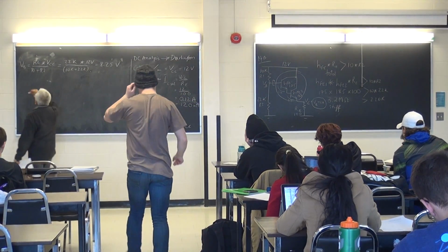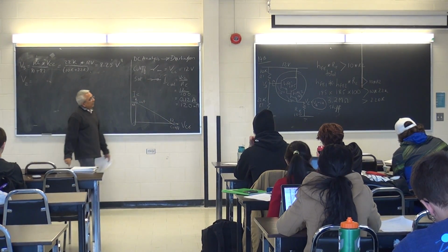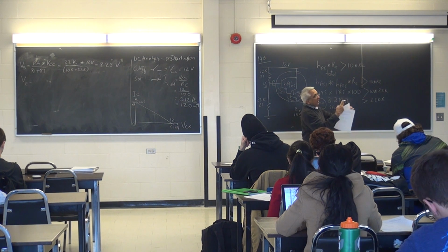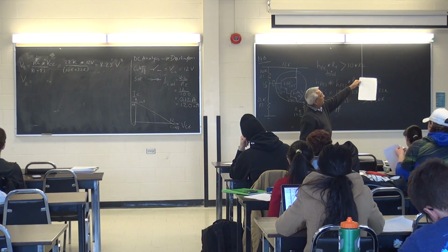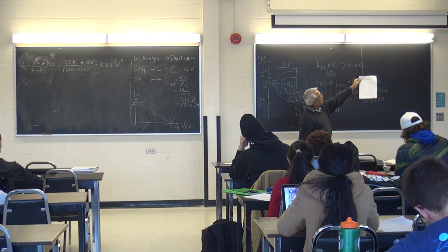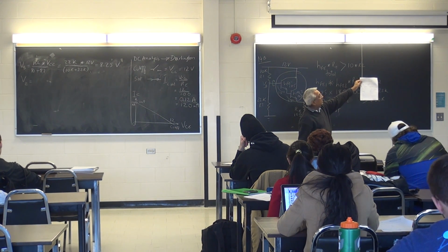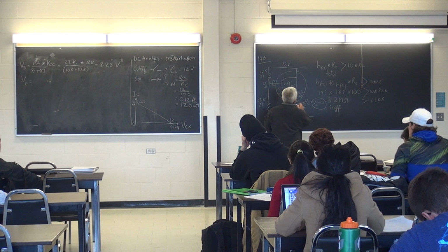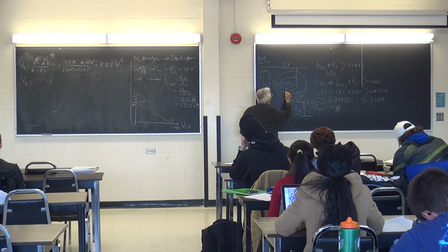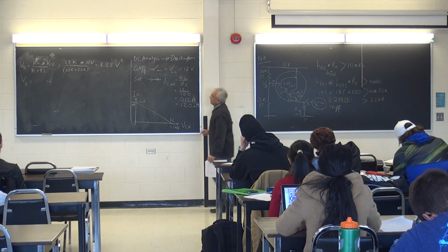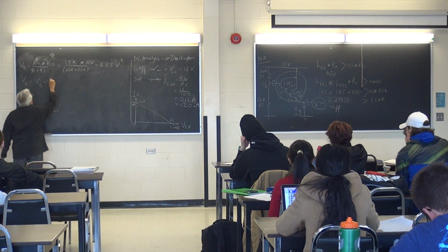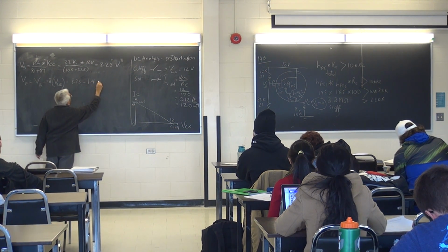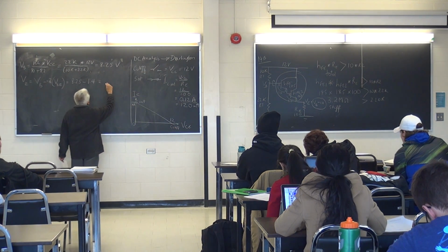Let's now find VE. VE is what? The voltage at the emitter to ground. So is that VB minus what? 1.4. This is also mentioned on the back page under Appendix 5, Darlington pair common collector amplifier circuit, DC analysis. Total current gain, beta total, is beta 1 times beta 2. And VE is VB minus 2 times VBE: the base to emitter of the first transistor, base to emitter of the second transistor. So it's VB minus 2 times VBE, 8.25 minus 1.4. How much? 6.85.